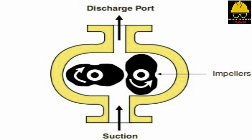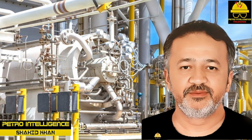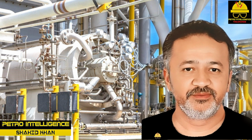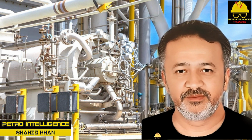The rotation of the lobes may be up or down, that is, the discharge port can be at the top or at the bottom of the unit. In dry service, the upward rotation is preferred. In wet service, the downward rotation is recommended so any condensed liquids can escape. Lobe compressors can be used as compressors or vacuum pumps.